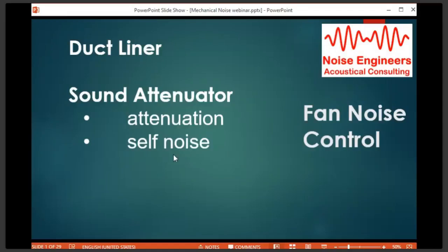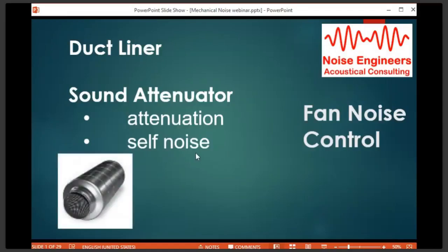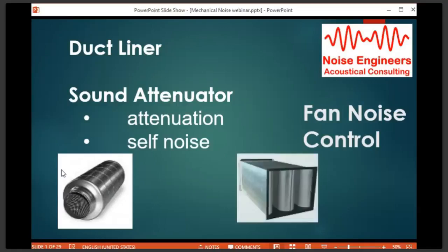There are tables of, given the amount of flow, what noise is generated by the silencers. So this would be a rectangular and a circular, but notice the flow is constricted quite a bit. And they need to be properly sized, but they're going to generate some noise. But if you're trying to attenuate low frequency noise, these silencers are a great option.